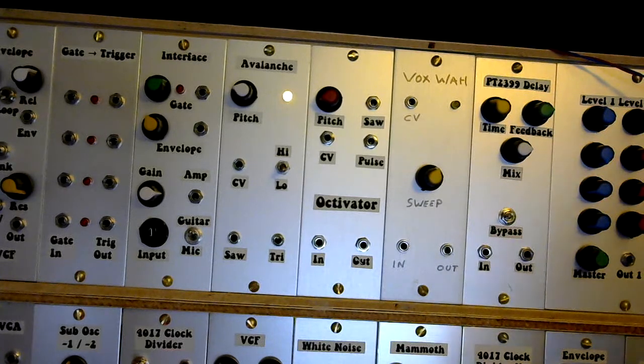I will say, before we move on to what it sounds like, I've just remembered the one thing I did find, and I don't know why this happened. When I plugged it into 9 volts, which is what the circuit was designed for in the first place, it worked fine. Plug it into a plus 12 volt supply rail, the VCO still worked, but I couldn't get the binary divider to work. And I don't know why, because it's supposed to take up to something like 20 volts. So 12 volts should not upset it, but for some reason it just didn't want to work. Whether I got some wiring wrong or whatever, I don't know.